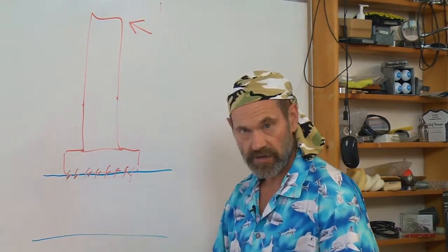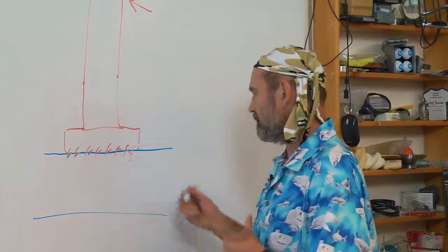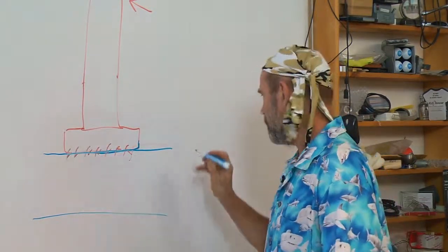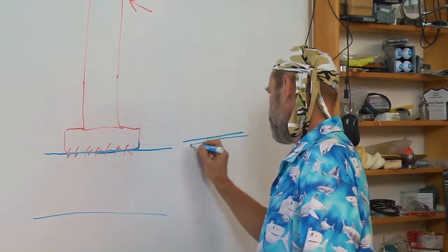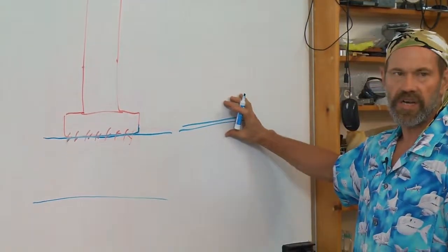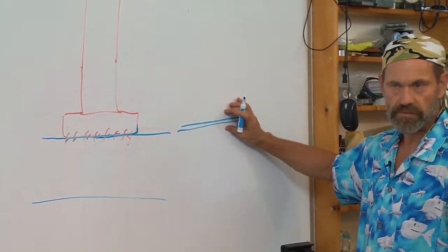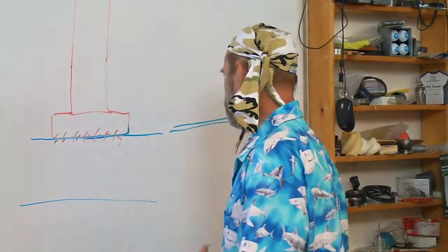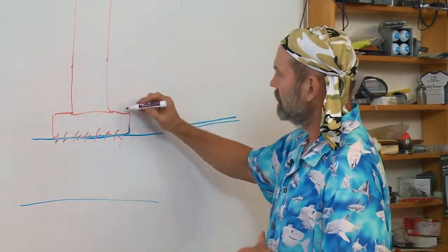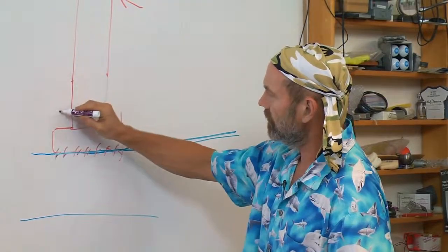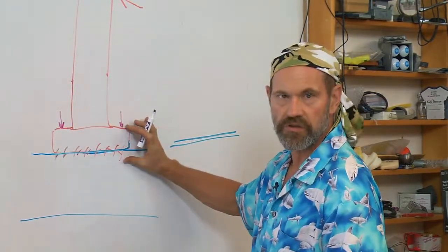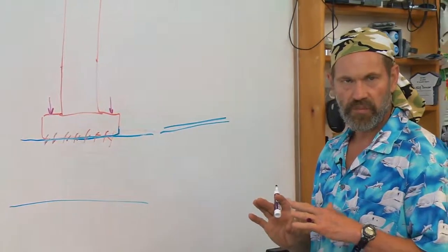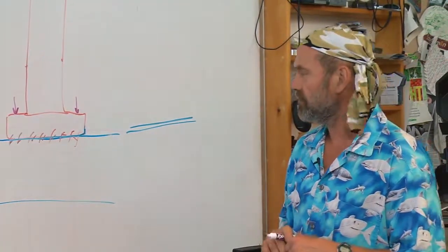In a more advanced modeler, you could specify this joint in here as what's called a gap joint. It can open but not close. Then what you would have to do is apply forces around the joint to emulate the bolt forces. That is one way you can do this, with a more powerful finite element tool.